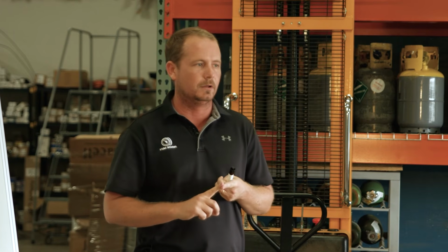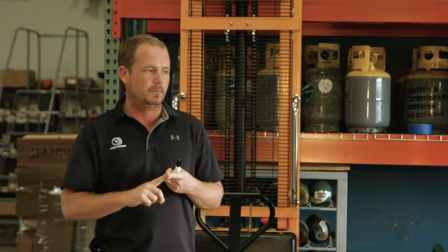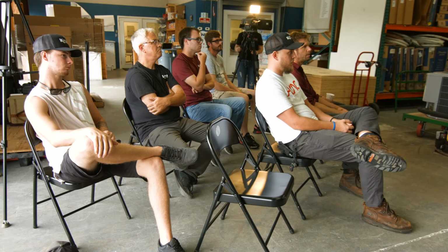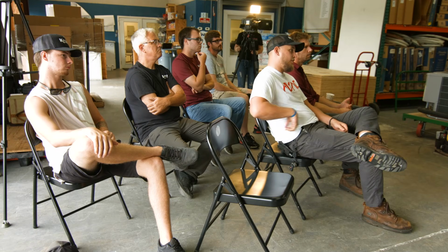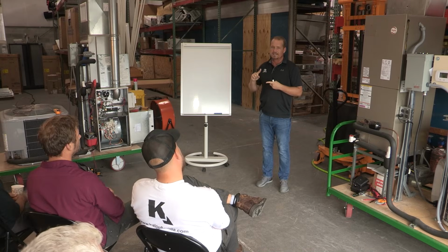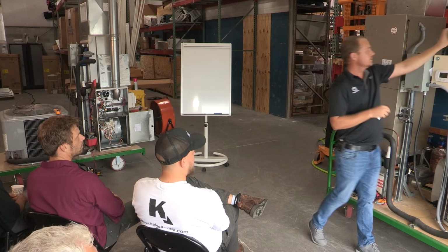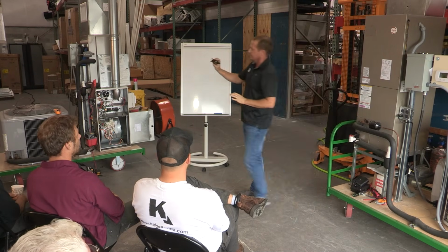When we talked about cooling versus compressor versus contactor, all of those are true in one sense, but where's the problem with saying that Y is the cooling call? What's the problem with that? Heat pump application. In a heat pump, it's your contactor, right? It's what specifically energizes the electromagnet on your contactor. Let's grab a contactor here quickly. So what is Y really?